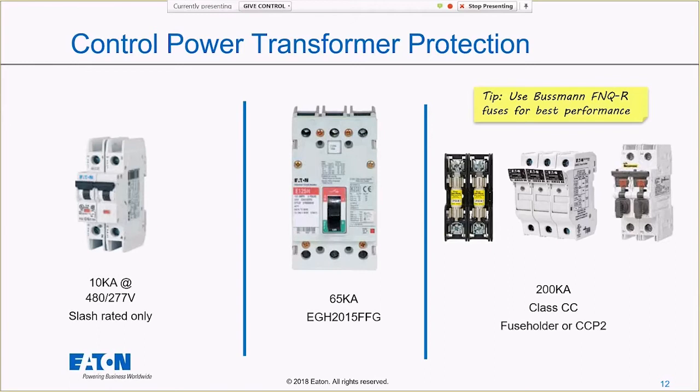It is absolutely a shock hazard if you do. So whenever we use a fuse holder like that, we just really, really want to be careful that we're not using that as any sort of load break. I know that's really probably on the end user who's going to be doing that more than the manufacturer, but just know that that's sort of a risk in using something like that. Particularly, I think, in front of a control power transformer.